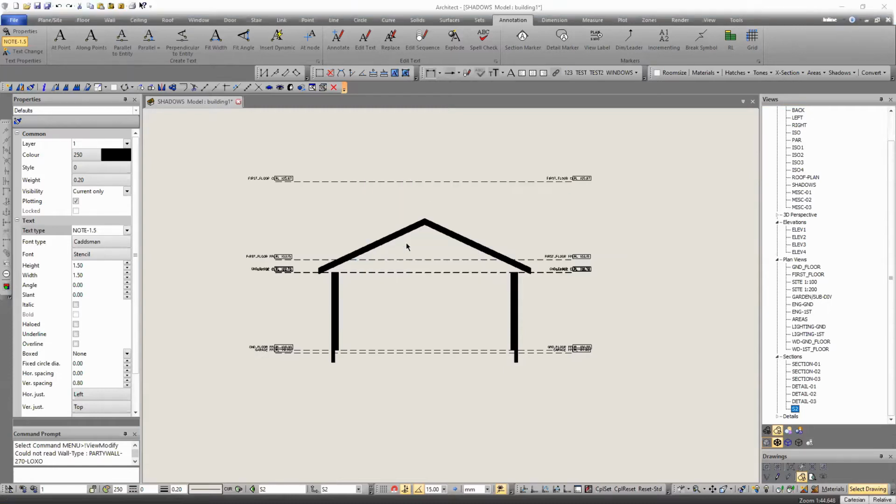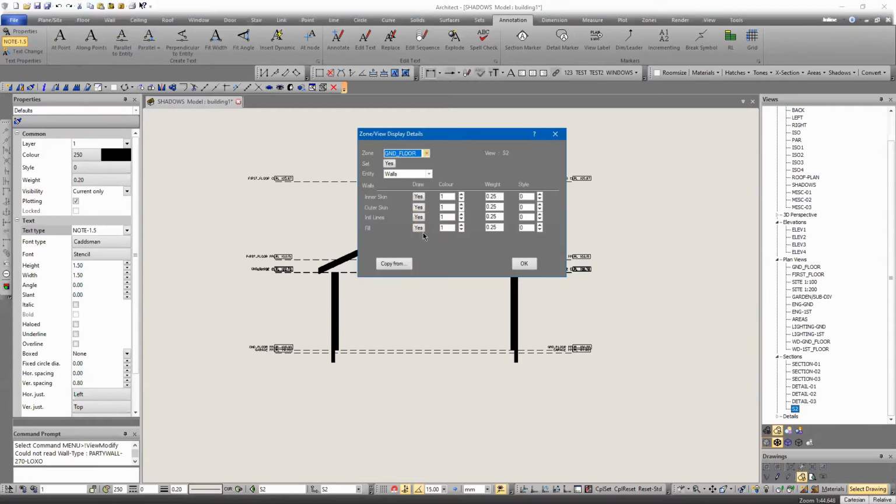Particularly if you've got a material that appears sectioned one way, like in plan, you'd show the material one way, but in vertical section, you would want to show it a different way. That's one of the ways to then turn it off here. But the problem is you sacrifice all. So all of your wall fills will be gone if you say no.